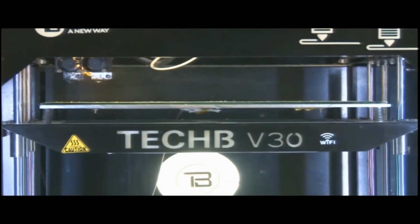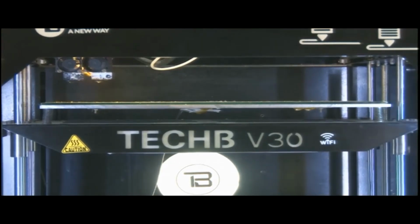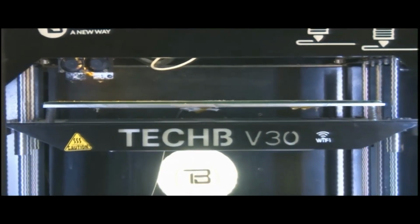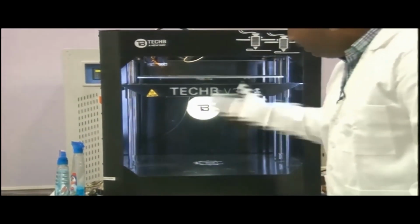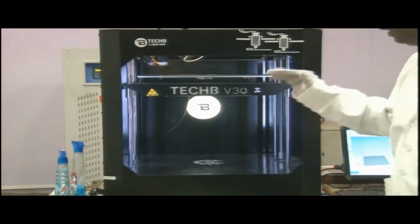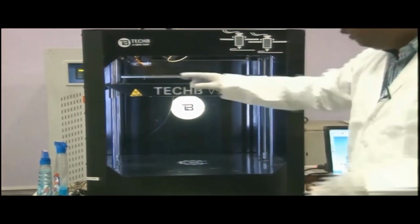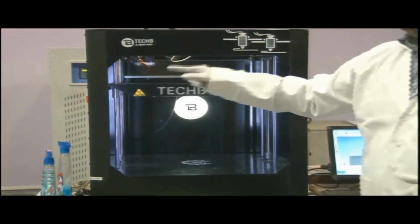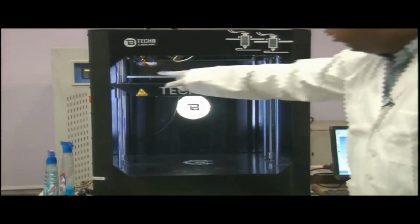In this software we can set the slicing layer thickness to 0.1, 0.15 or 0.2, the 3 levels here. Whenever we change this layer height parameter, we need to maintain the gap as well. Say I have fixed 0.15 from the top of the bed to the tip of the nozzle.